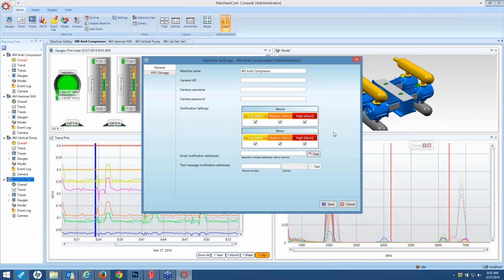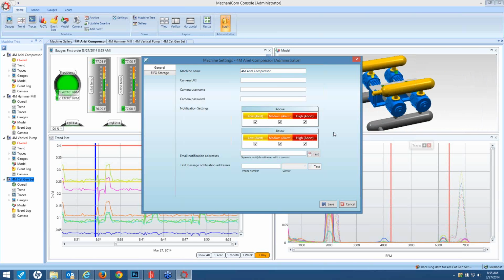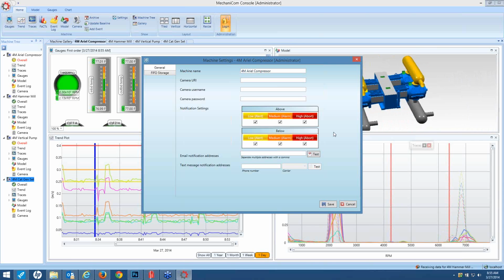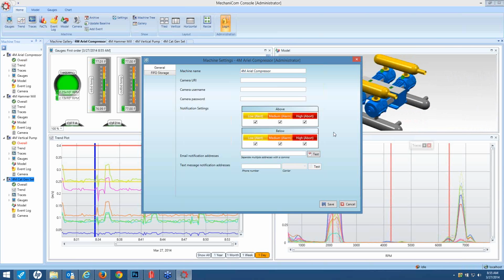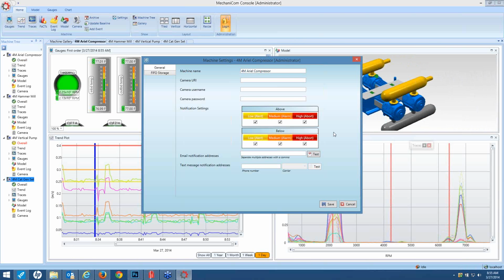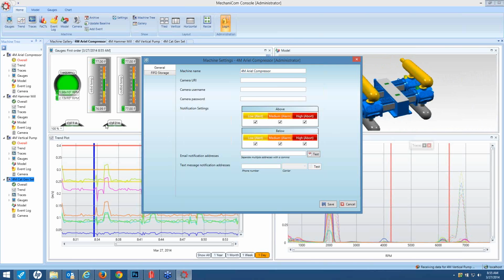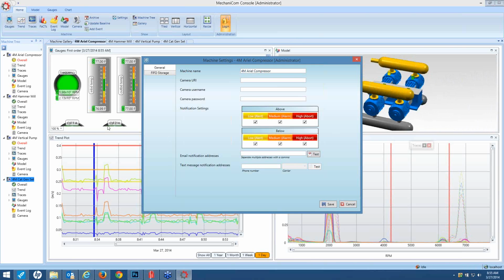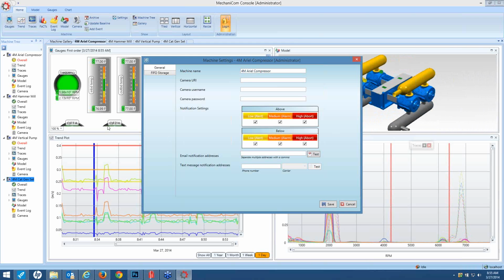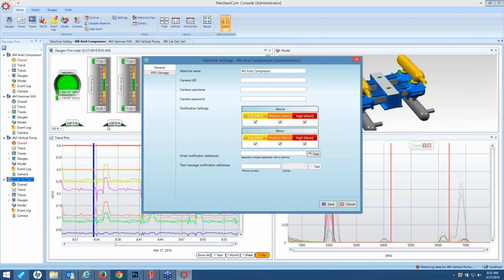We also offer the option to use relative alarming, which would mean that you set the number relative to your baseline measured amounts. Your thresholds are set to that. So if you want to set for a percentage away from your baseline for temperature, if your baseline temperature here is roughly 75 degrees, if you wanted to set a percentage away for each of those levels, you can do that, and I'll show you how to do that. Or you can set values relative to that baseline. But most of the time, we just work in absolute values, and that's kind of the standard that you would do.